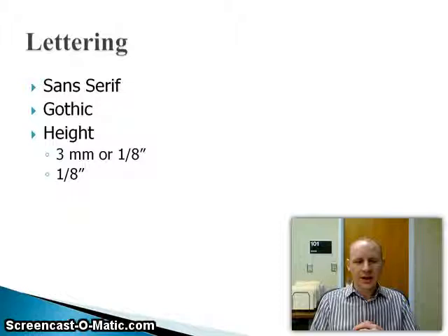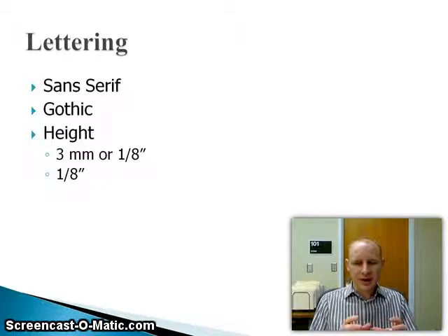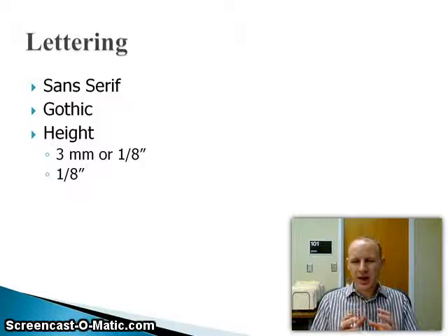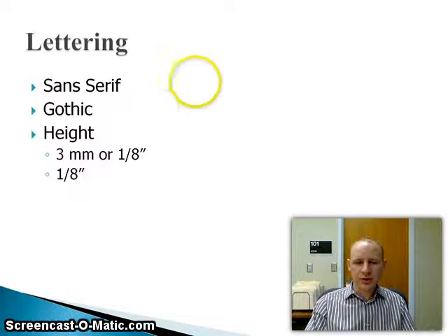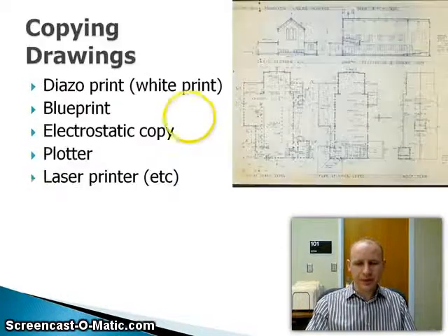As we do the height of our text, the standard height that we traditionally use is an 1/8 inch. As we're putting dimensions on a drawing, as we are doing different lettering throughout the drawing, the standard size is 1/8 inch. We may have some larger titles that may go up to a 1/4 inch, but the standard size font we use when we're doing drafting is an 1/8 of an inch.